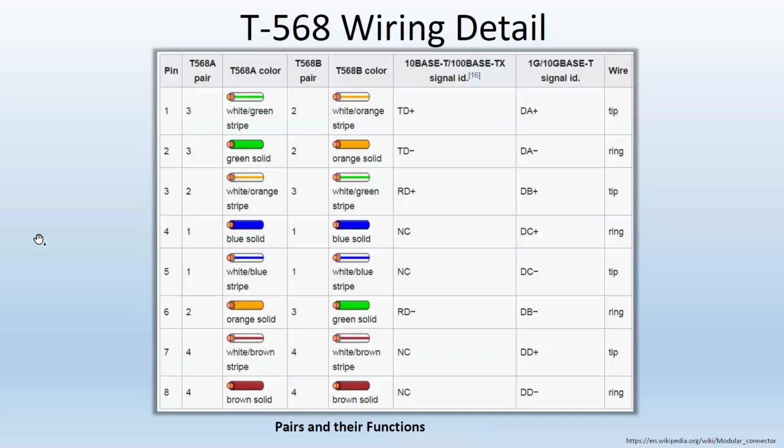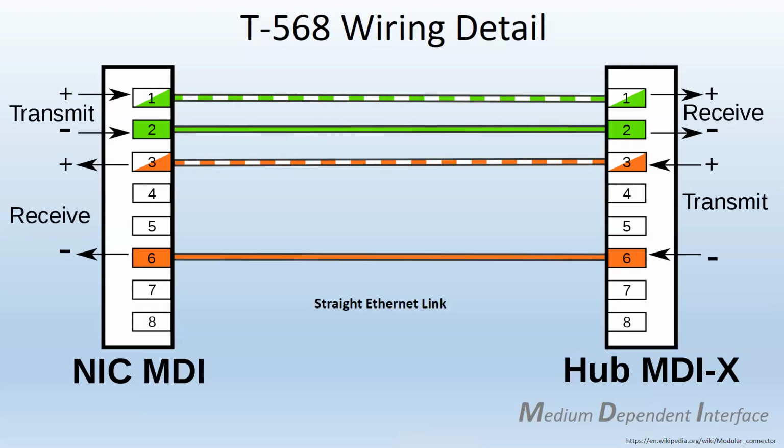All right, so let's see here. That's why this is a scheme or schematic, or a way of terminating Cat 5e. In fact, when you see some of the less expensive patch cords or connecting cables, when they are spec'd for Cat 5e, sometimes you're going to see a jack like this and a jack like that, or a plug in the cable, and the prongs in the plugs, those two middle prongs and pins 7 and 8, are going to actually be missing any kind of conductor, and the cable is going to look lighter and more flimsy because you're going to have only greens and oranges there. That's it.